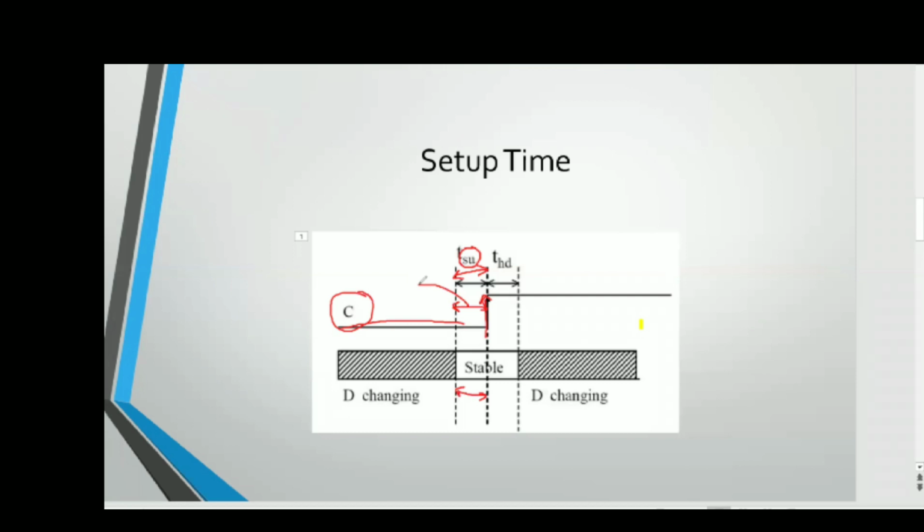So basically, we all know that we have two things in VLSI which come all the time together. That is the setup time and the hold time. So friends, this C is nothing but the clock. This is the clock which is coming, and you can see that at the positive edge of the clock it is changing its value. So the clock is arriving at this point, right? So this is the window where your data should remain stable.